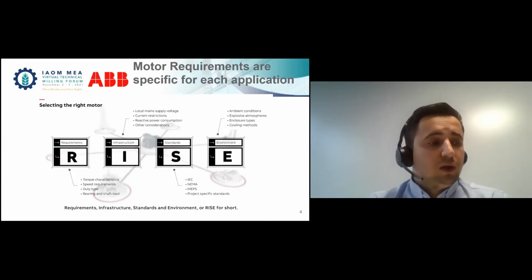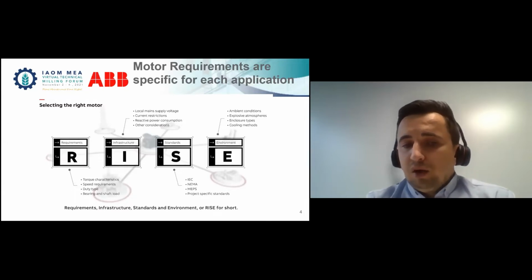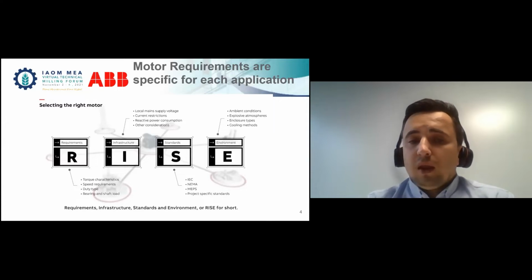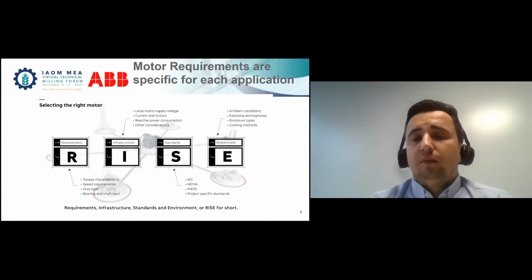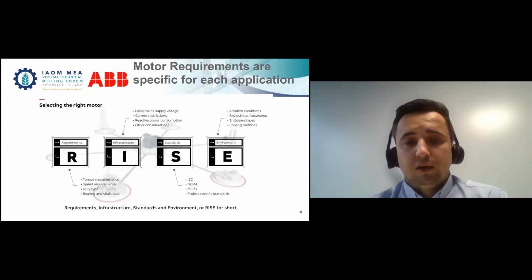So if you don't configure it properly, as an example, if the shaft load is too high, then this can lead to very dangerous situations where the bearing can be damaged and create a shutdown of this particular application or machine, or it can even harm more stuff or create a dangerous situation.